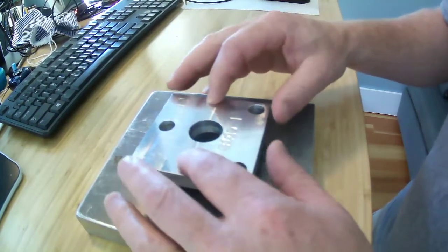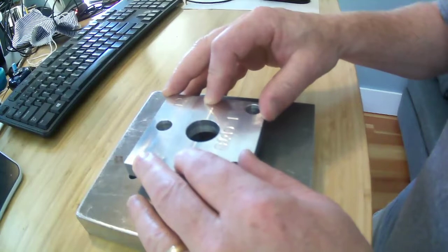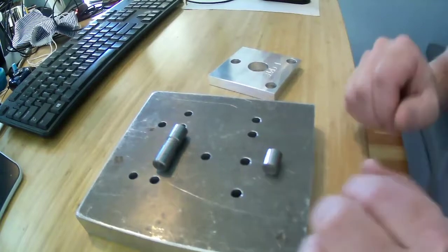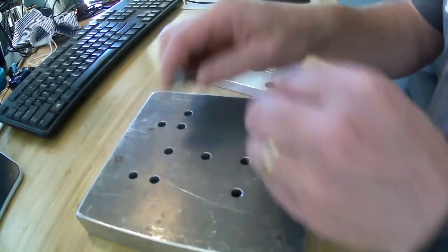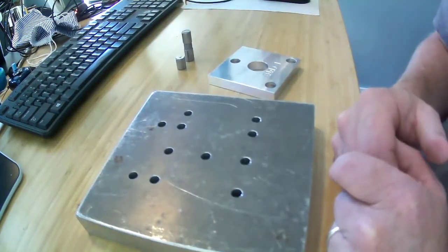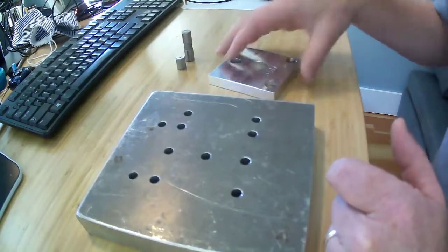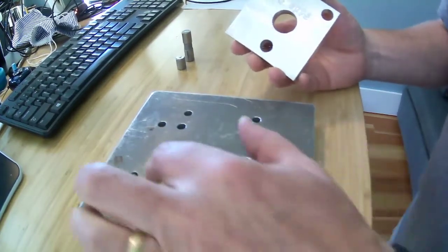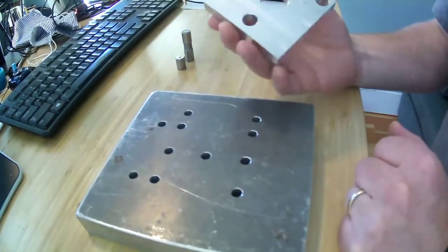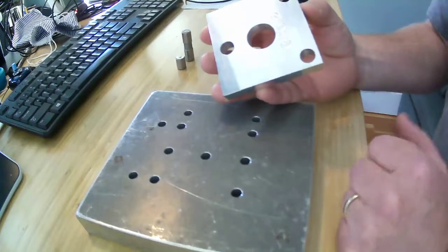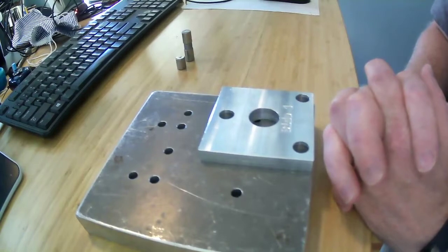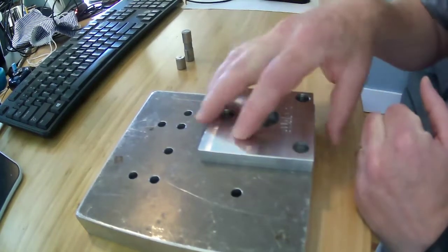Okay, getting better. And I can't feel a wobble in that one. So my determinism is getting better at each one of these steps. I hope you see some of what we mean by improving determinism or increasing determinism. When we get to the point where we touch these two, and we know exactly where on this surface the two contact each other, then we have complete determinism. But there are some downsides to getting it too small.